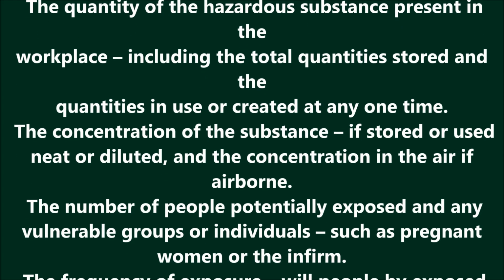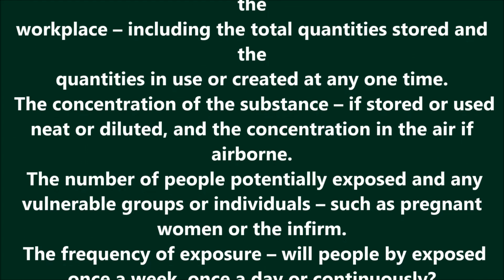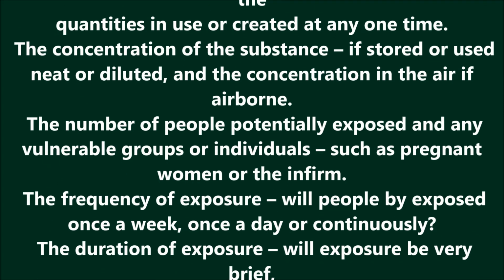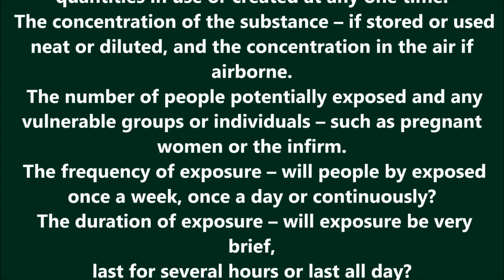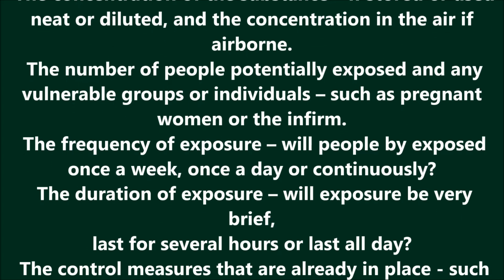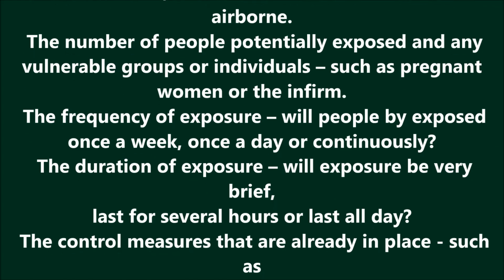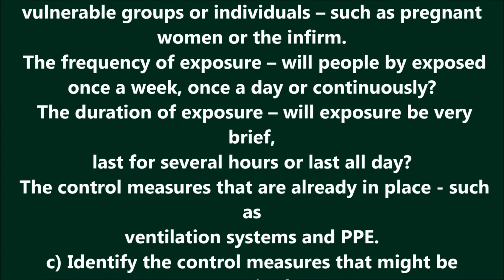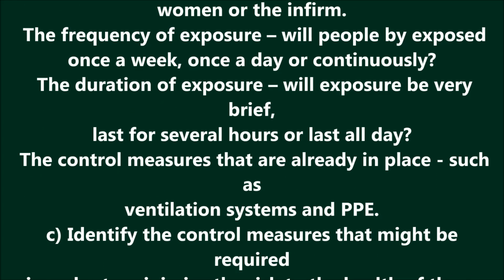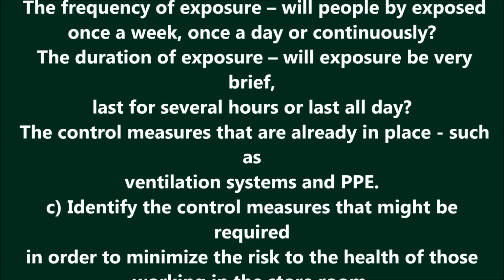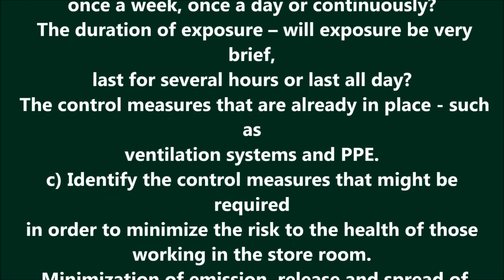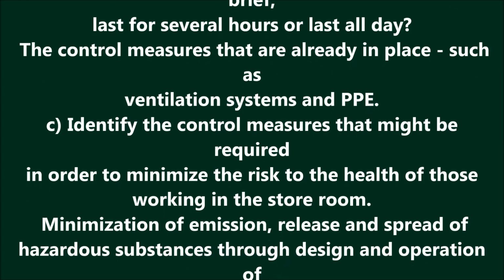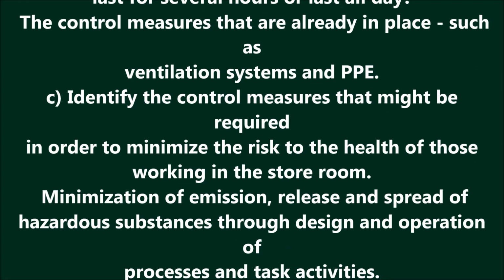The concentration of the substance, if stored or used neat or diluted, and the concentration in the air if airborne. The number of people potentially exposed and any vulnerable groups or individuals, such as pregnant women or the infirm. The frequency of exposure. Will people be exposed once a week, once a day or continuously? The duration of exposure. Will exposure be very brief, last for several hours or last all day? The control measures that are already in place, such as ventilation systems and PPE.